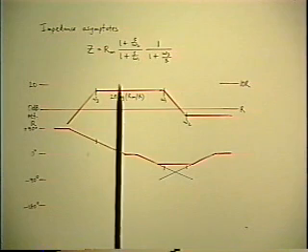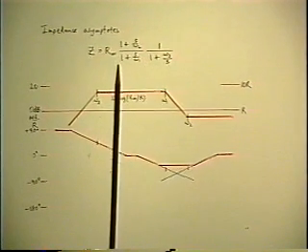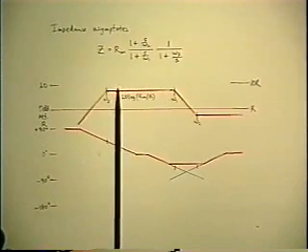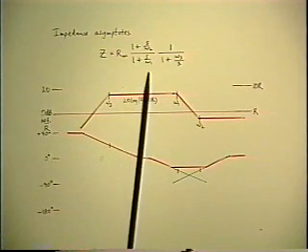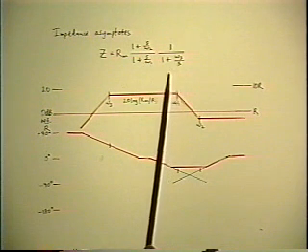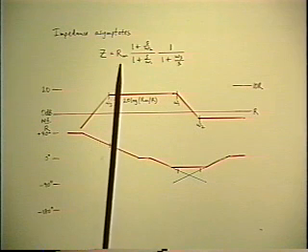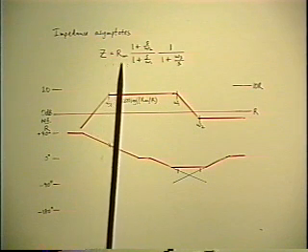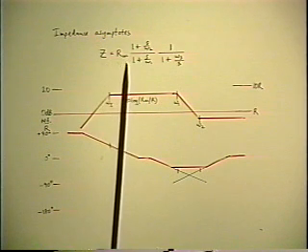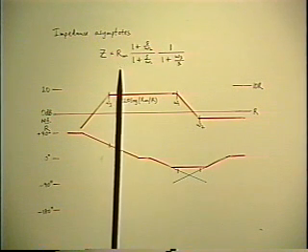Here's an expression for an impedance. Let's not worry about what circuit it comes from. It's in factored pole zero form. And two of them are normal, one of them is inverted. And the only extension needed from the previous notation is that the coefficient in front now has the dimensions of a resistance, sort of the scale factor.